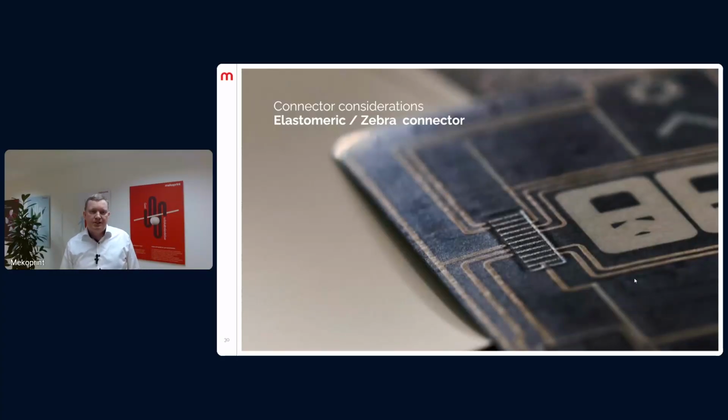Another type we see used is an elastomeric or foam connector, also called a zebra connector. So here it has a little bit the same advantage as the spring connector in that we don't need a tail section, which again reduces the foil outline complexity. But then it has, on the other hand, the advantage compared to the spring connector that you can have finer pitch designs. The disadvantage is that you need to have a very uniform compression force, and the foam may harden over time.